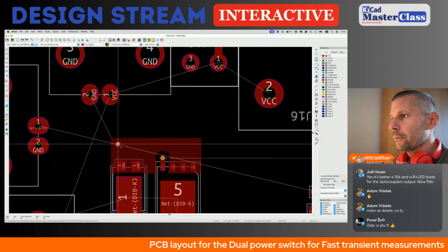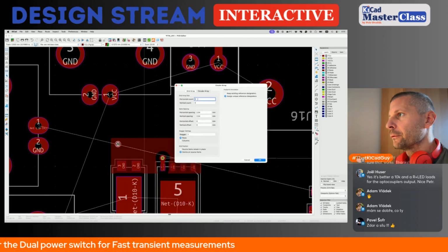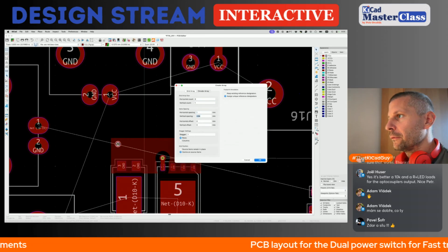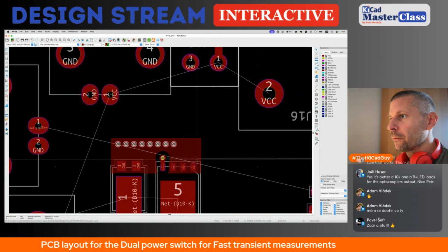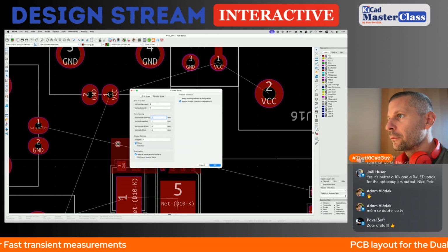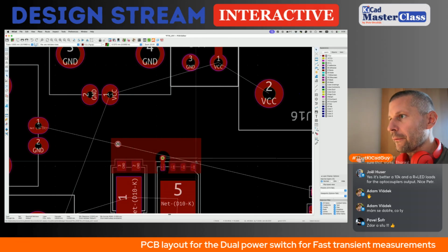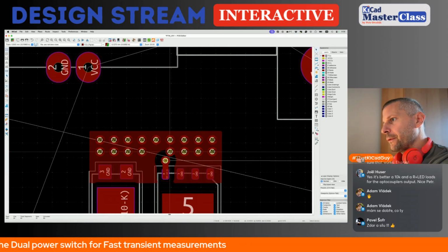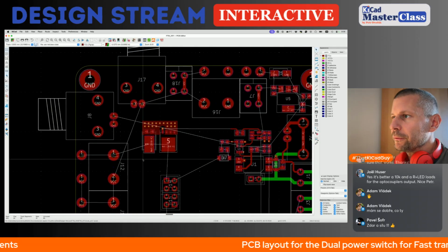Okay. With a bunch of vias. Horizontal, I guess 8. Let's try. Yeah, that can work. I think a little bit far from each other. Further from each other. Yeah, so I think 9. Into 2 rows, with the exception of this. Okay, that can work. Now the big cooling polygon.